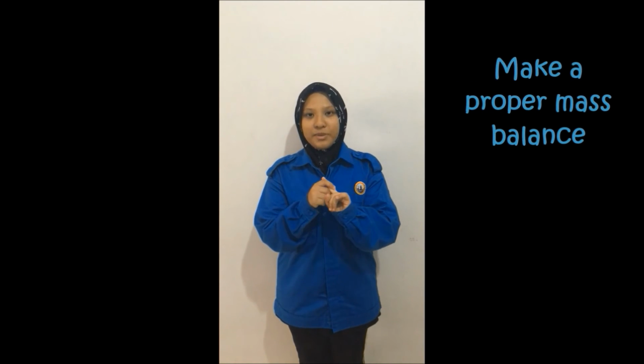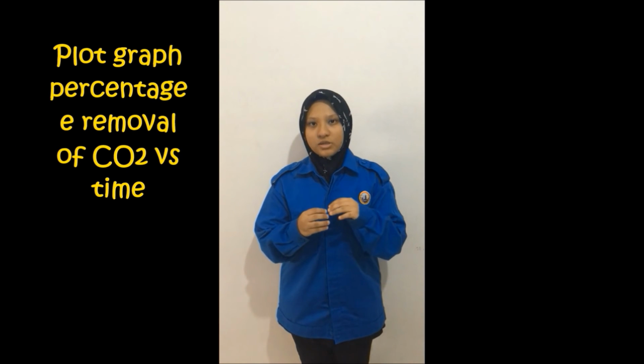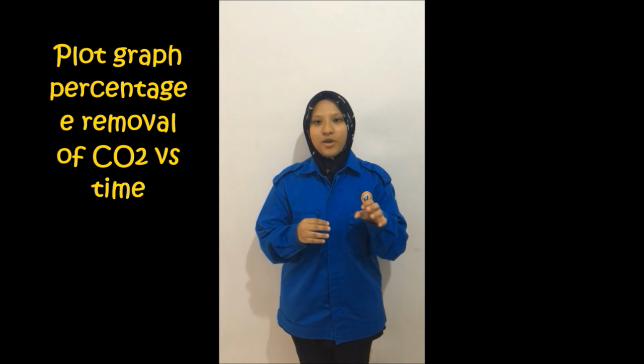In the analyzing and discussion part, we have to do two things. First one is make a proper mass balance to calculate the percentage removal of CO2 from the absorption column, and the second one, we have to plot a graph of percentage removal of CO2 versus the time, and we discuss the effect of air flow rate on the percentage removal of CO2. To undergo these two steps, we need to do a proper calculation. So let's have a look at the calculation.